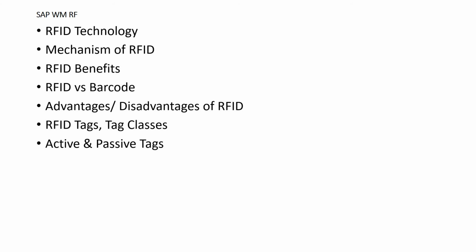Passive tags can be read at a distance of up to 4 to 5 meters using the ultra high frequency band, while the other types of tags, semi-passive or active, can achieve much greater distances: up to 100 meters for semi-passive and several kilometers for active. These large differences in communication performance can be well explained by the IEEE associations, right?